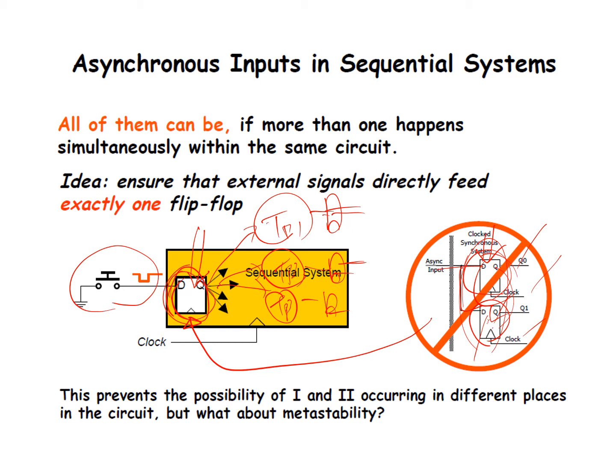But even with a single flip-flop, if this one fails, then all the paths will fail, right? Because once metastability happens, we cannot guarantee the timing can meet the defined clock period. So having a single flip-flop makes the situation less bad, but it cannot completely remove the issue.